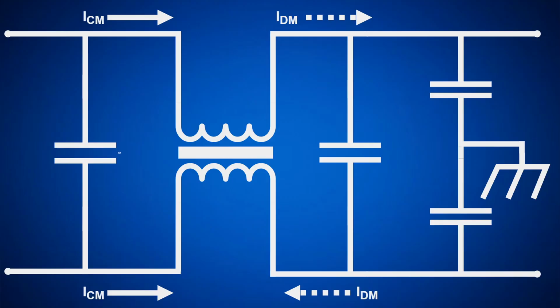Another way you can deal with common mode noise is to simply filter it. When it comes to filtering out common mode noise, there are specific filter configurations that you should utilize. One of the filter components is referred to as a common mode choke, and it is essentially just two inductors that share the same core. Each inductor carries current from two places. Typically, it's power and ground, but you can technically put this on any pair of signals.